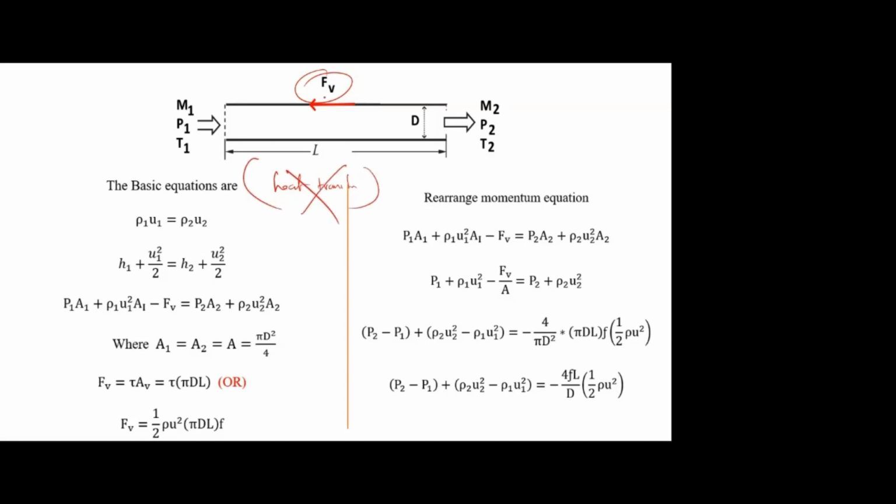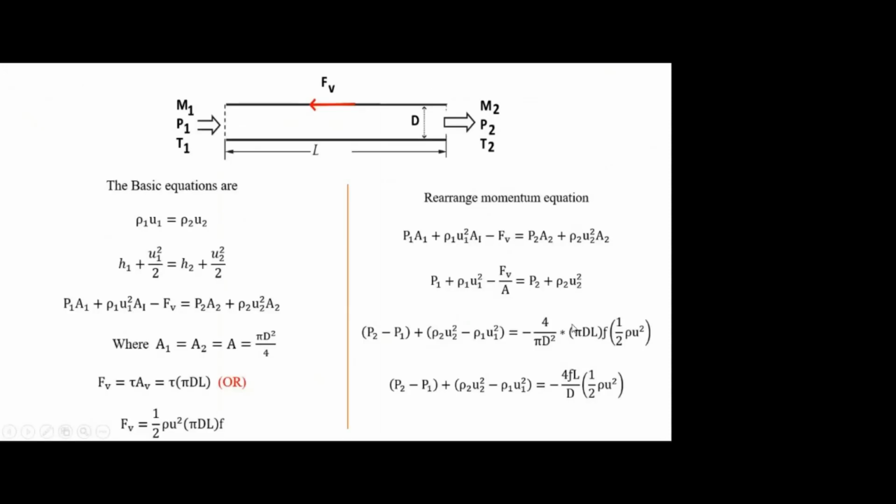We know even due to the viscous effect there will be a small heat generation, but we assume there is no heat generation here. So here, due to the viscous dissipation, only P naught is reduced, T naught is constant, unlike normal shock, oblique shock, etc. Here also, subsonic flow will be accelerated maximum to Mach 1, and supersonic flow will be decelerated to maximum Mach 1. So here also we are taking one long duct.